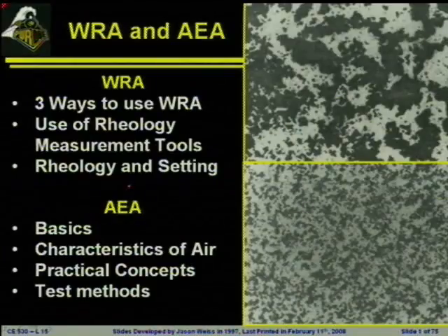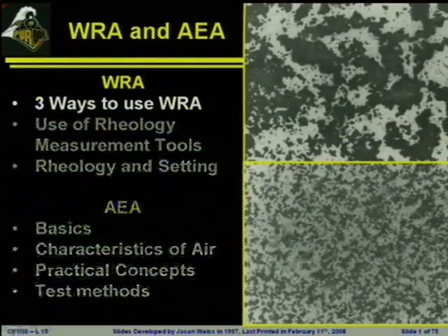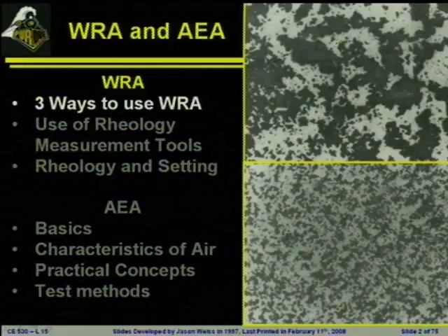You'll remember we've got a picture on our right-hand side. The top picture is the system that doesn't contain a water reducer. The bottom picture is the part of the system that does contain the water reducer. We know the big difference is that the water reducers act like a dispersing agent. The water reducer is there to essentially neutralize the charges on the cement particles and to disperse the particles from one another.